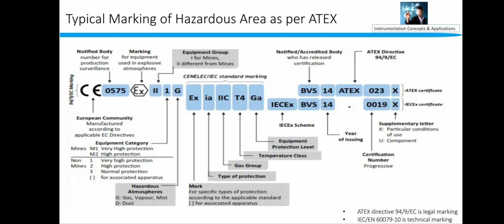This is the typical marking of a hazardous area as per ATEX directive 94/9/EC. First you can see that CE is mentioned. This is European Community, manufactured according to the applicable EC directives. After that, there is a notified body number, which is 0575.